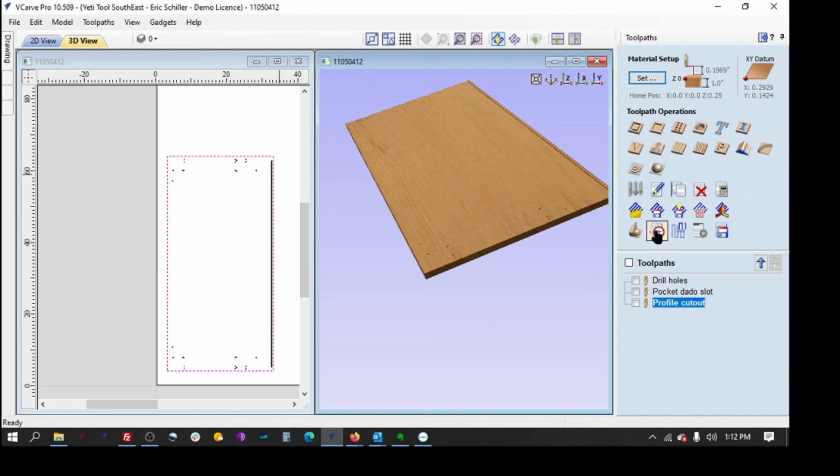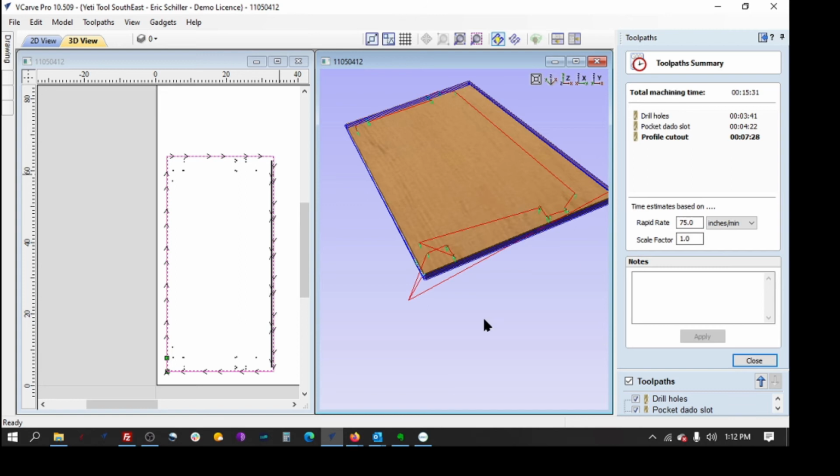If we look at the machining times, that's probably about right. The border cuts, I can probably cut at 150 inches per minute with a 1/4 inch depth of cut with a 1/4 inch spiral O is my guess with most resins. But we'll just leave it at this. So we're saying 15 minutes per with Pec drilling. Who knows? I would just print this out.